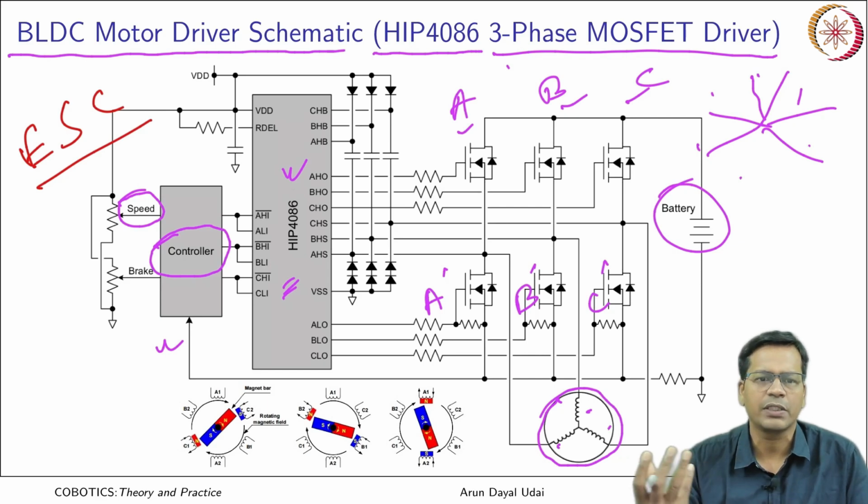So those actuators don't have feedback, they run on an open loop because the load is not variable. In case of quad rotors, the load is not variable. You precisely know how much load is going to come. Accordingly, you select a motor of precise torque, a little higher torque actually, so that it never fails, it never slips. And whatever angular velocity you command, it actually goes there. You don't need feedback because your rotor doesn't get stuck anywhere, it is not overloaded at any time.